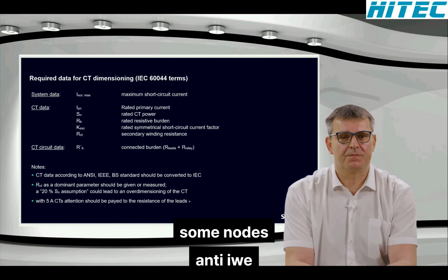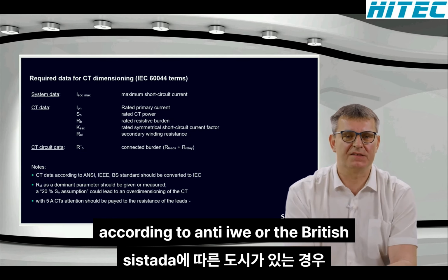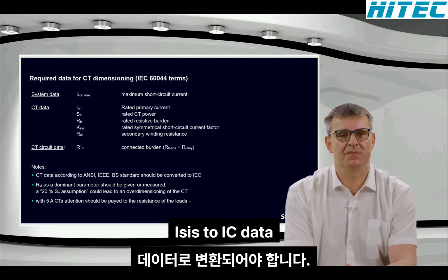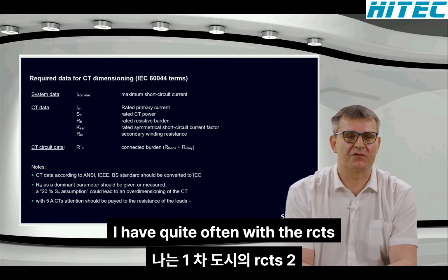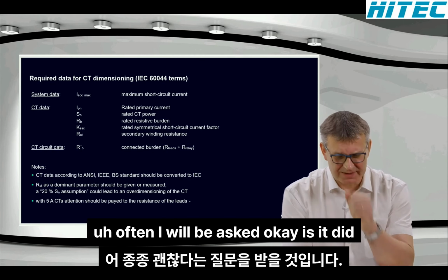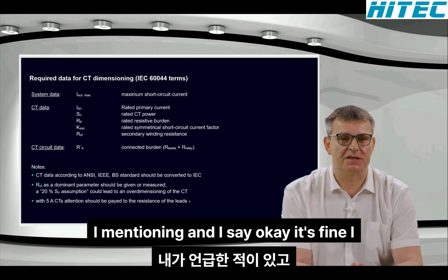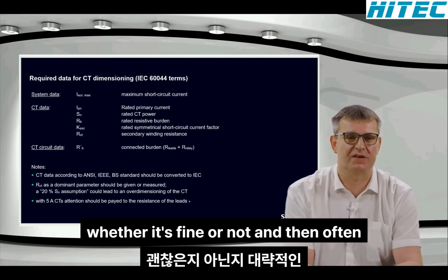Some notes. If you have CTs according to ANSI, IEEE, or the British standard, this data should be converted to IEC data. I quite often have a lot of problems with the RCT, the secondary winding resistance of the primary CT. Often I am asked about CT dimensioning, and I say I can make a rough calculation for you whether it's fine or not.